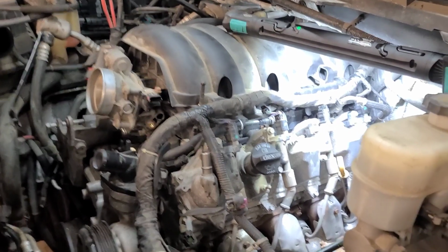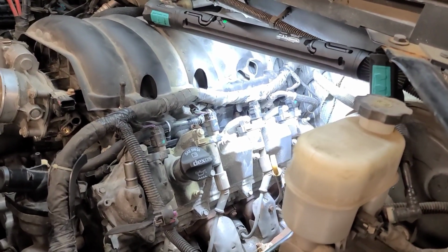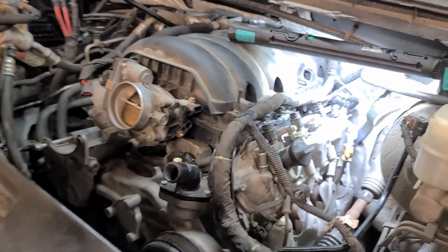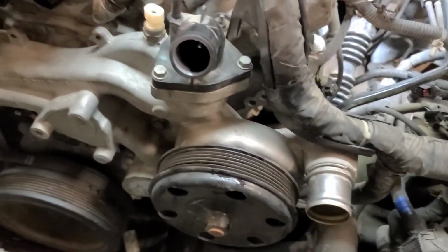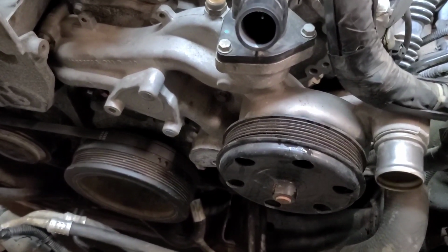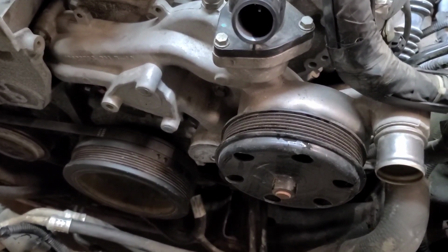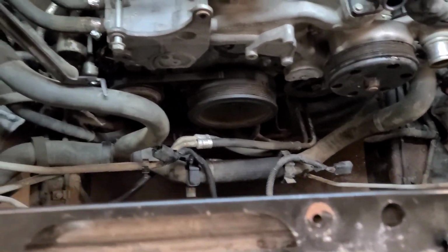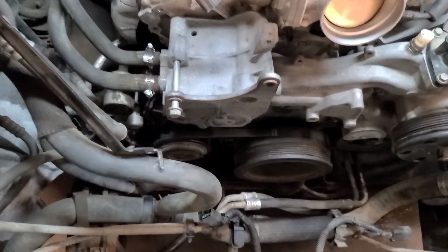Well, there's the wiring harness mounted, the intake manifold on, AC compressor on, 2 stretch belts on. I find the AC compressor belt easiest if you use a tie wrap through the harmonic balancer pulley, and then walk it on by turning the engine. New hose clamps on the heater hoses. I was just about to put the belt tensioner on,